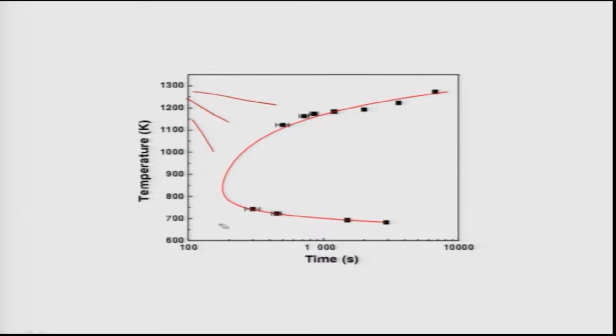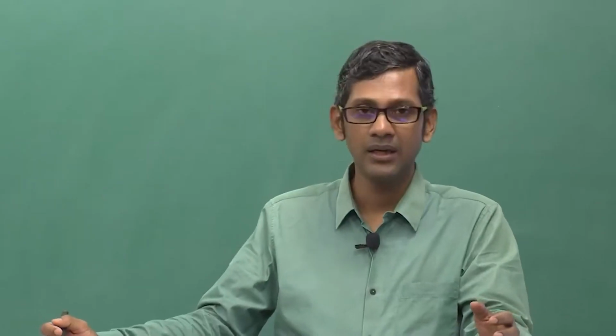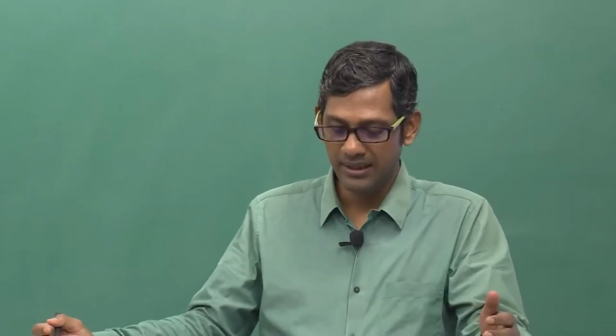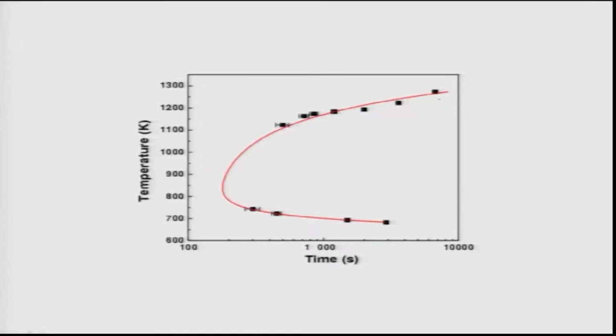But remember, how much transformation will happen from the gamma phase, for each of these phases, will depend on how the transformation process takes place. A typical pearlitic transformation, which is nothing but a diffusion controlled transformation, involves both nucleation and growth as distinct steps. The transformation will look like a C curve. Why? It's very easy to understand why it looks like a C curve.